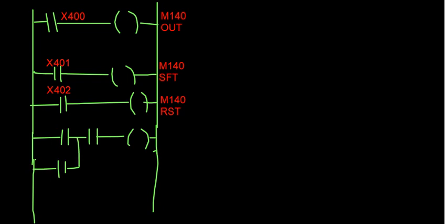You know what exactly M144 is? This is the fourth bit of your relay which is responsible for the deflection, right? And I am using one internal relay here, M100, and again this will be the same M100 here. So now please see here, after this I would use the final rung which is required for me to have the deflection of items.